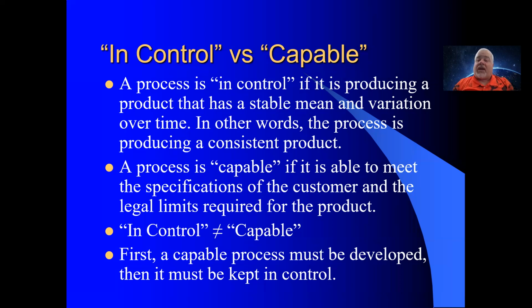Or maybe it is with some minor updates. Maybe I can update my machinery or slow the machines down, or maybe there's something I can do to meet that customer's specifications. Maybe there's not. But again, the control limits are based on what your machine does. The control limits don't give a dang about what your customer's specifications are or what your customer wants.